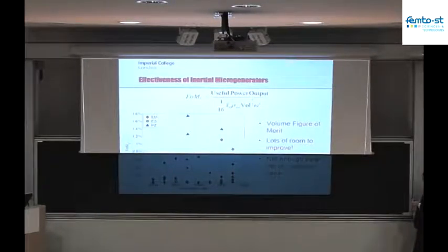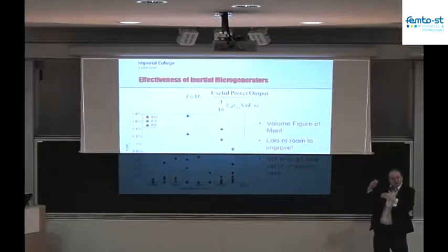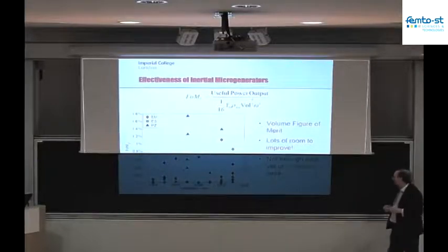So what I can do to effectively try and increase the displacement of the fundamental in my system is to add in a little bit of third harmonic, pull the amplitude of the system down a bit, and then decrease the damping factor a little bit in the fundamental to allow the new motion to expand to cover the entire range of motion. Remember, what I'm trying to do is maximize force times distance.